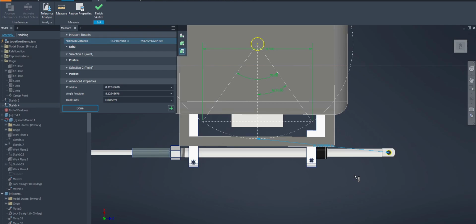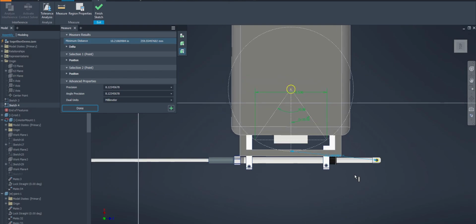because this thing right now is sitting at the halfway point in the rod throw, and the motor is sitting at center. So that means theoretically when I turn all the way one direction, it will get to the 35-degree limit, and then turning the other way, it'll be the other 35 degrees, giving us a 70-degree sweep overall.